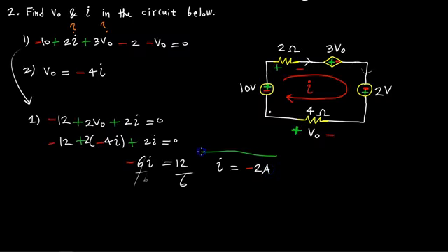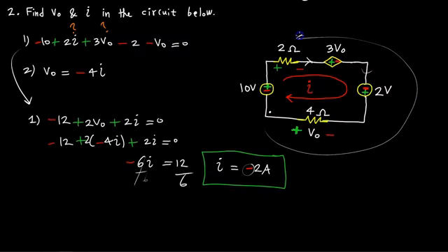And we're seeing a minus current. Not to worry, all this is telling us is that the direction that we indicated here is not the true direction of the current flow, conventional current flow. That's important to keep in mind. The conventional current flow then is going opposite due to this negative sign. It's going opposite of what we indicated. So the real current flow is going in this direction.